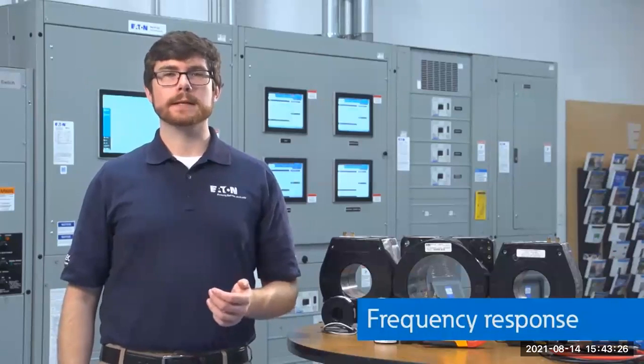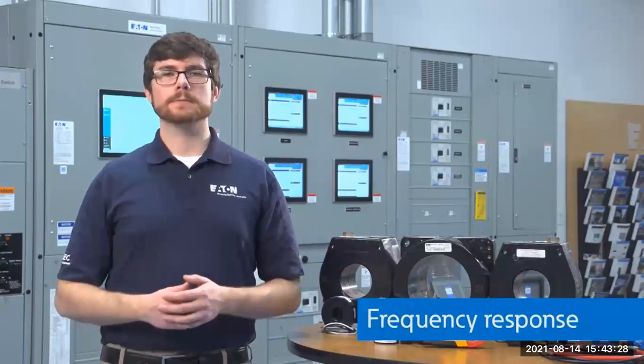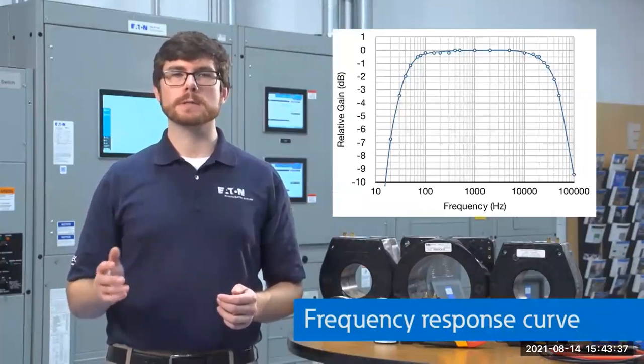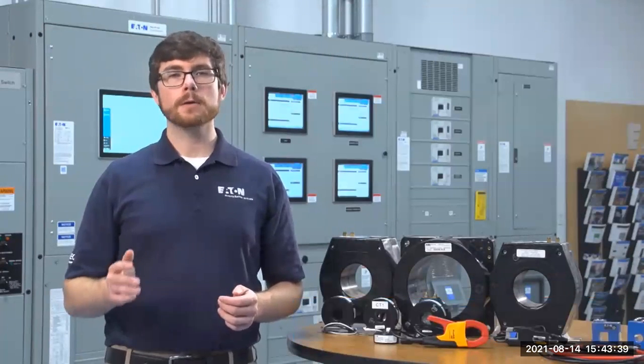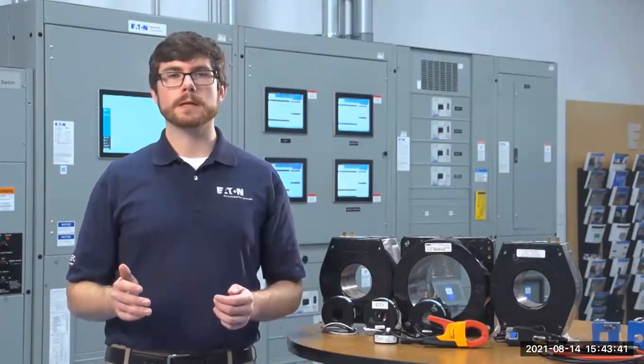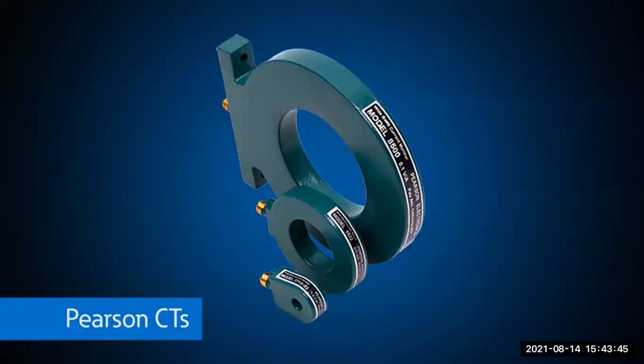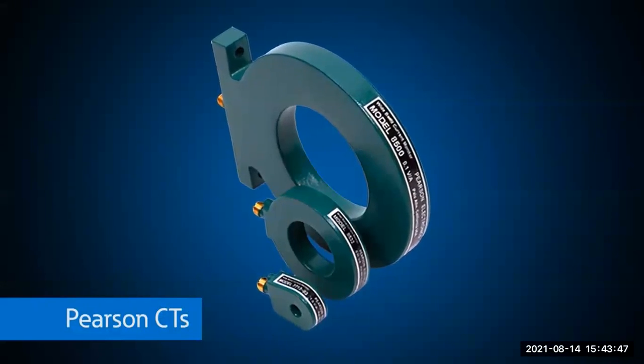In addition to CT saturation, the maximum frequency range that a CT can measure is typically 3 to 5 kilohertz. For most applications, this is okay since the harmonics on the power system are typically within this range. However, for high-frequency applications like transients in the hundreds of kilohertz or megahertz range, special highly accurate CTs like these Pearson CTs can be used.